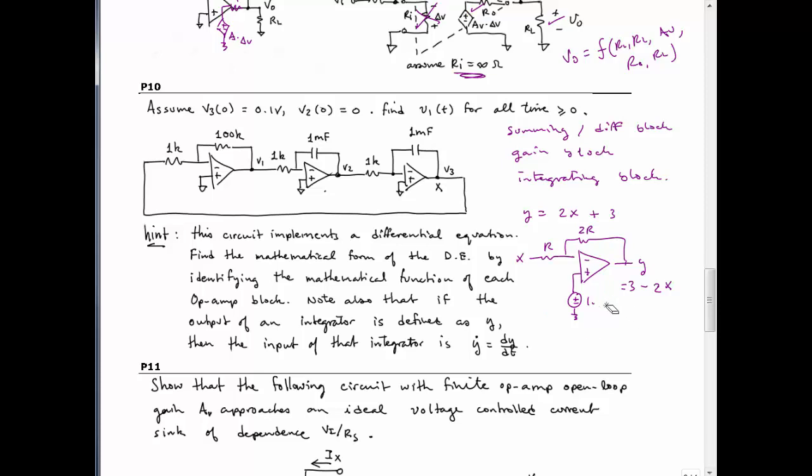But now I'd have to change this voltage here, because my non-inverting gain is 1 plus R2 over R1. So 1 plus 2R over R. So 1 plus 2, or 3. So I would need to make this 1 volt, right? 1 times 3 is 3 volts.